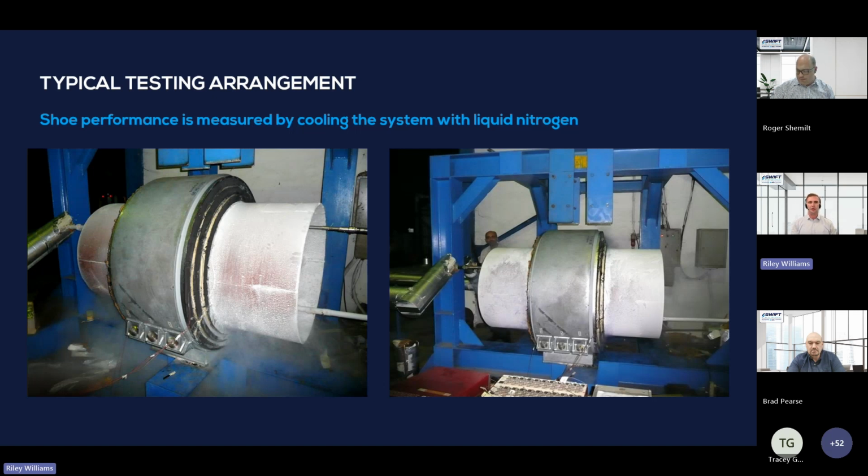This tells us whether the PUF insulation is doing its job, which is to sustain the cryogenic temperature inside the pipe consistently. Afterwards, we send the PUF off to a lab for destructive testing, and this includes closed cell content, compressive strength, water absorption, and flammability testing.